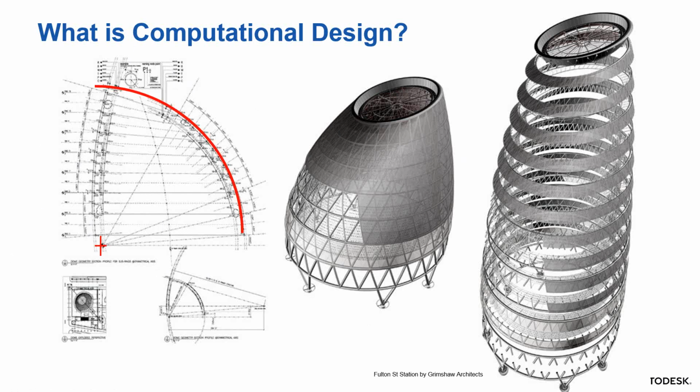They built essentially a small computer program using the visual programming techniques that we'll talk about to handle how to lay out the geometry, how to slice it up by different levels, how to build the superstructure that's all tube steel, and how to build the interior hanging cable net that supports these shiny metal panels that are going to reflect the light. And it was really effective for them because they could not only handle that from a design standpoint, but carry that information all the way through the construction process and into fabrication.